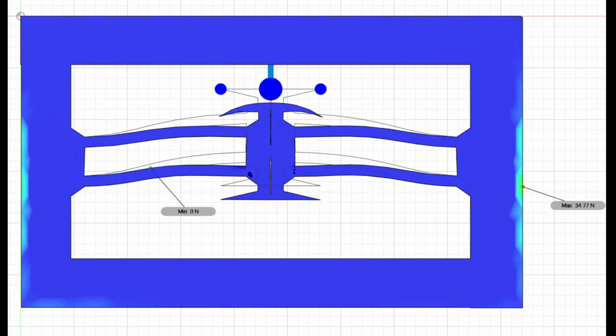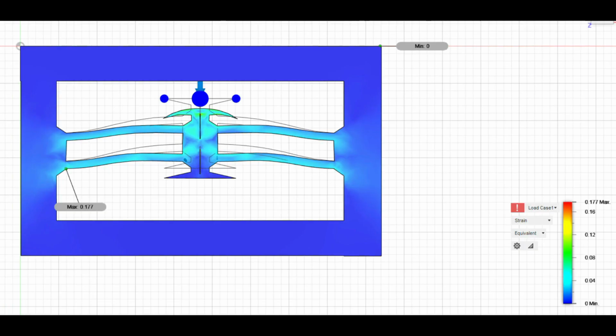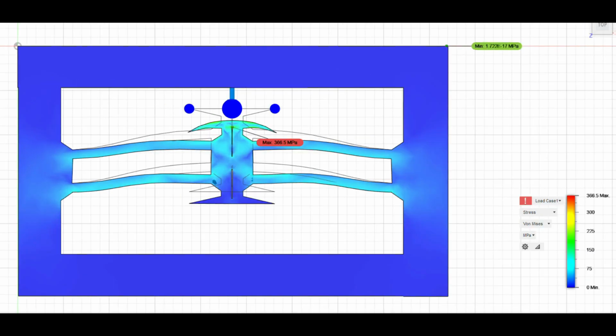On a miniature model scale, we assumed a 50 x 50 x 10 mm model made of ABS plastic, which was 3D printed with sufficient support structures, and obtained 5.54 mm of displacement under a load of 10 kilos.